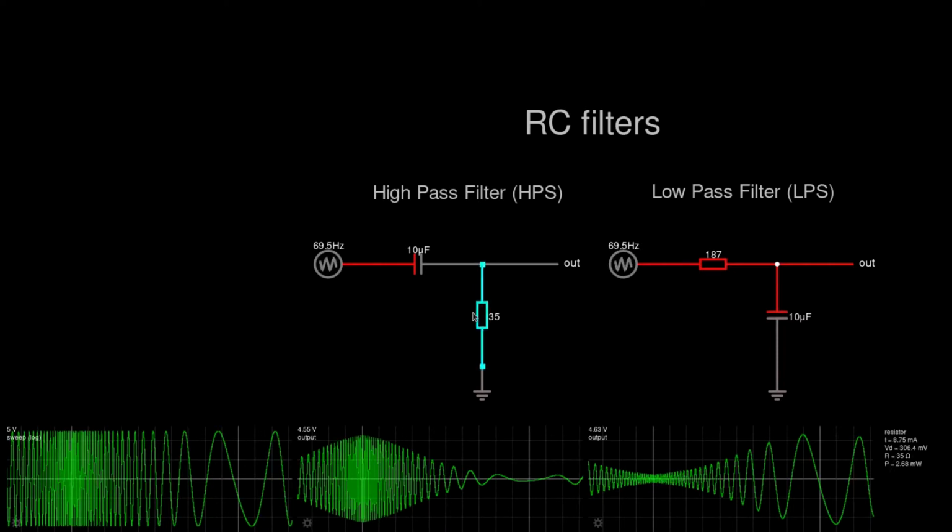And so this one has a higher value than this one, and that's why the output voltage, which is actually the voltage drop on the resistor over here, is lower. And the higher the frequency, the lower the resistance over here, thus the higher resistance would look like over here, and on higher resistance we get higher output voltage.